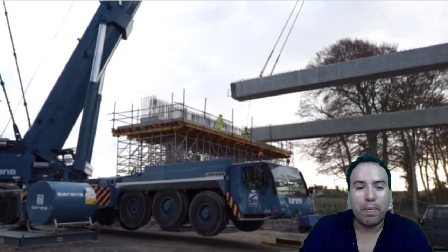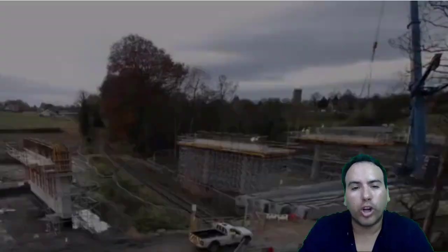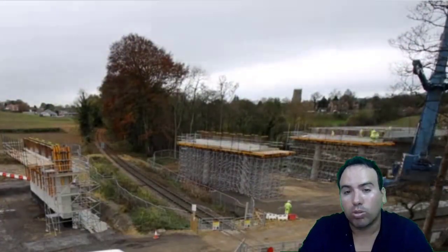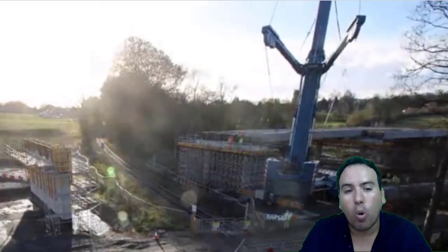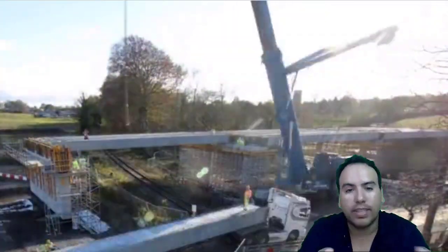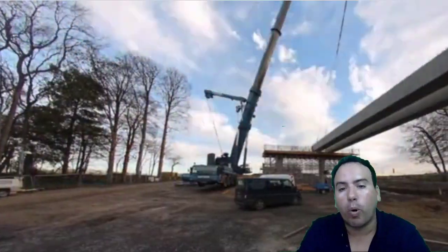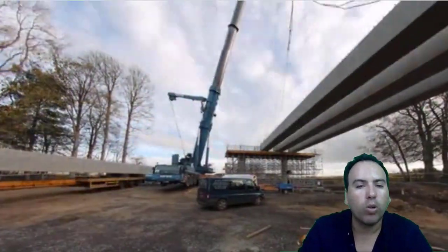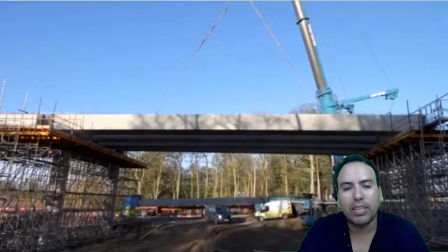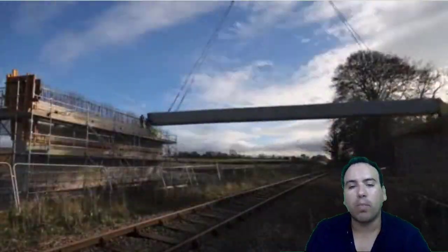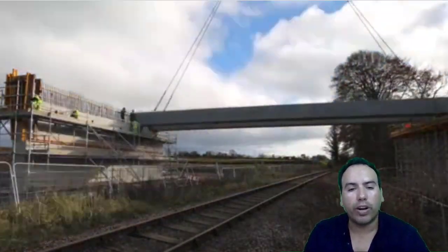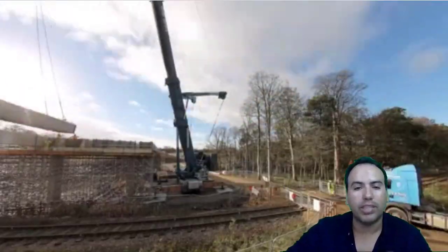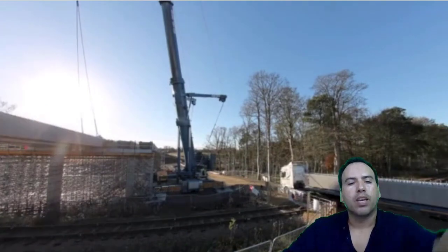Now, beams. The beam is a horizontal structural element that withstands vertical loads, shear forces, and bending moments. The loads applied to a beam result in reaction forces at the support points of the beam. The total effect of all the forces acting on the beam produces shear forces and bending moments within the beam that in turn induce internal stresses, strains, and deflection of the beam.